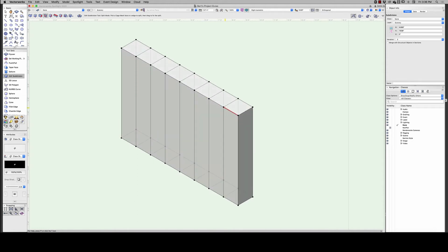Now to do our 8 rows, we'll just do the same thing down the side. So we'll click here, tab 50, return, click here, tab 50, tab 50, tab 50. And if you don't want a specific number, you can just eyeball it, but I actually want a specific number here.